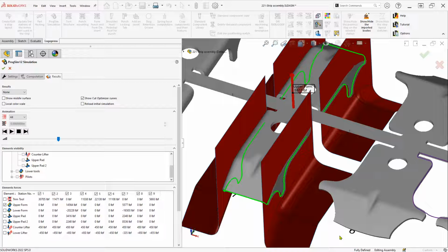And so the initial blank on this was done that way, Brad. We used what we call the LogoPress blank portion or the LogoPress flatten portion, the FEA one-step software for determining this blank, and that's what we fed into it and built the strip around that. And that's where you saw it was still relatively accurate on this part. You saw how big the slivers were, how big the areas were, I guess it didn't show you where it added on, but you saw where the leftover material was. But on some parts, you start to get more complex parts, and it can be incredible how much time it saves going in and out of the press. Yeah.